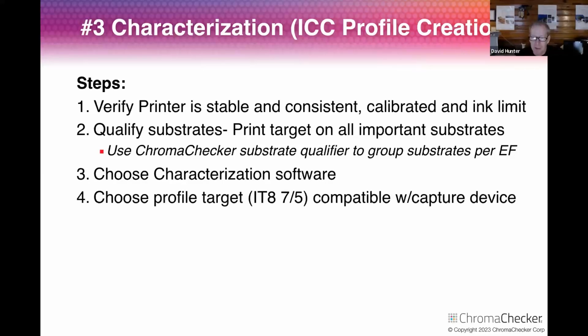with your measurement device. And when we're talking about measurement device, I'm going to chime in here that you want to make sure that when you're building the profile, you're thinking ahead, that when you're doing the quality control check after the profile is done, the measurement device that you're using to do the QC is in line with the measurement device that you're using to build the profile.